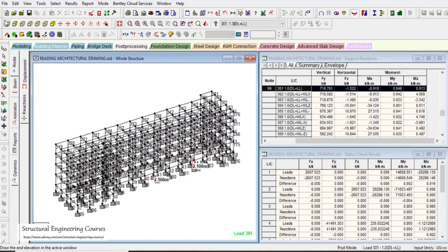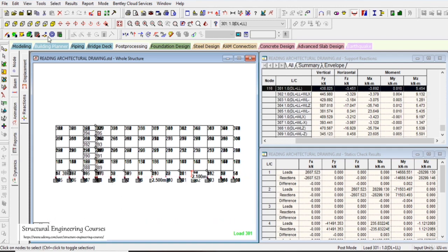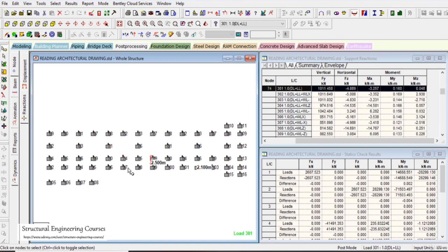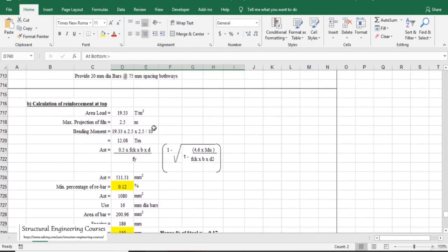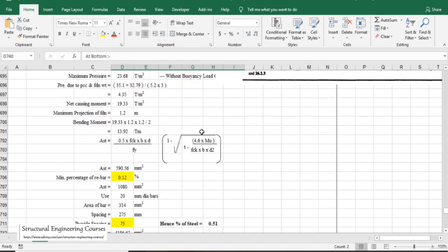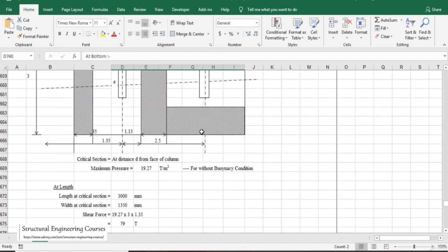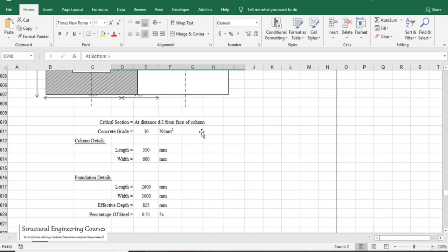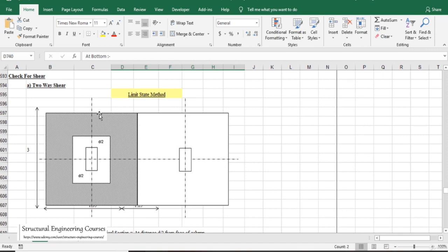As a trial, what you can do on your own is pick up any joints, let us say joint numbers 74 and 37, and then try to design the combined foundation. And I will suggest you please go through the Indian standard IS456 to understand what all the values here are that have been considered, and what one-way shear and two-way shear are. One-way shear, as I had explained in isolated footing also, acts at a distance of D, and two-way shear is nothing but acts at D/2.